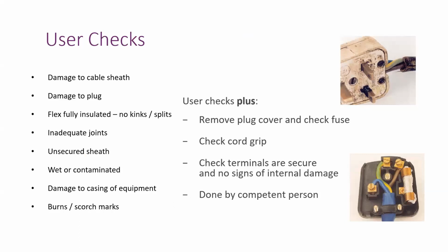So if you are not a technical person, not a skilled technician, or not an electrical engineer, then there is no need to open the electrical sockets or anything electrical. What we need to do is check physically for damage. If there is any damage to the sheet, the plug or the joints, or any contamination, or we find any burns, or the equipment is heating up. We can see these physical checks whenever we are going to use that equipment or power tool.